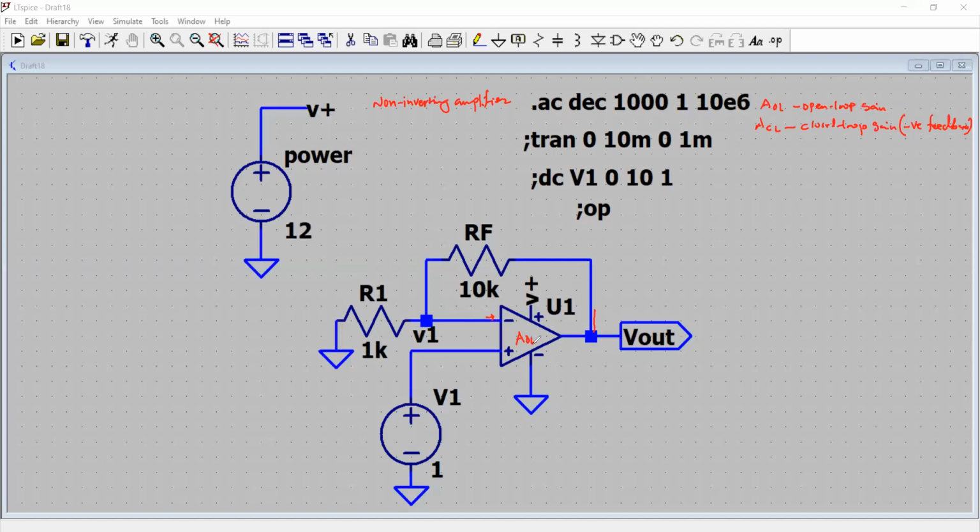So here you see a circuit where I have an amplifier as shown with an open loop gain AOL. Usually it's a macro model that I have picked up from the circuit simulator library. Please refer back to the previous video on the inverting amplifier to understand what a macro model is, how to use it, how to take it from the device library, and how right clicking on it gives you access to change the parameters like open loop gain, gain bandwidth product, offset, differential input resistance, etc. That part we have discussed in our previous video, so if you want those details, refer to that.